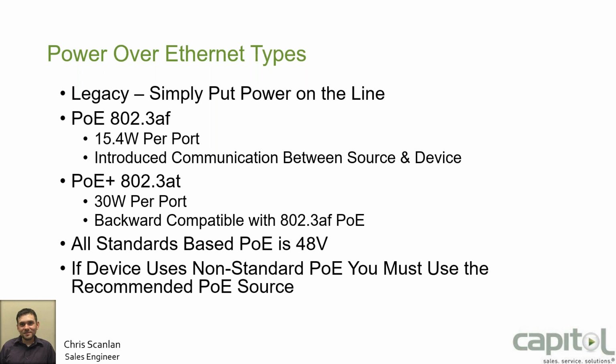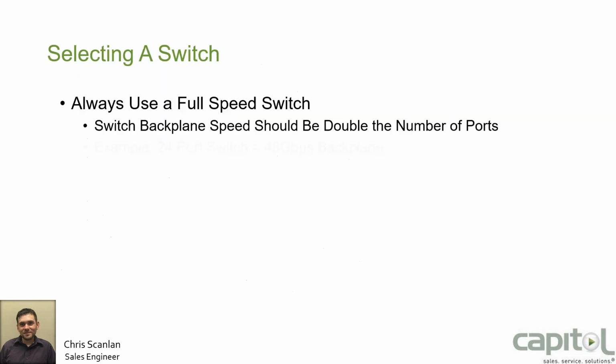So just be aware, if it says 12 volt PoE, it's not going to be able to plug directly into your PoE switch. A lot of times it'll be a step down transformer, which comes as a little box. That little box goes between your PoE switch or injector and the device you're powering.